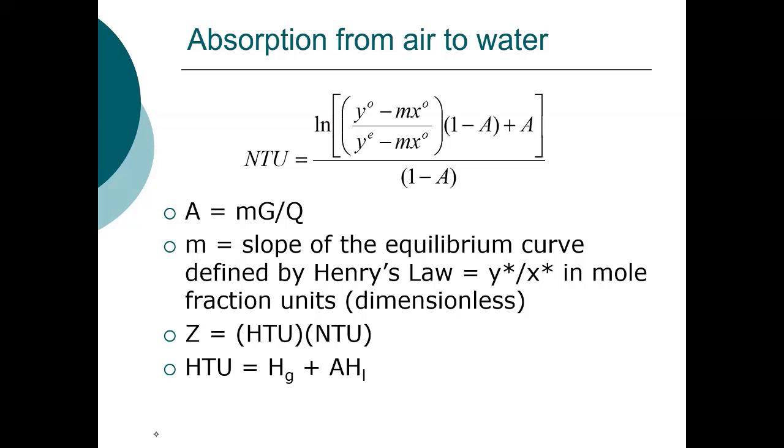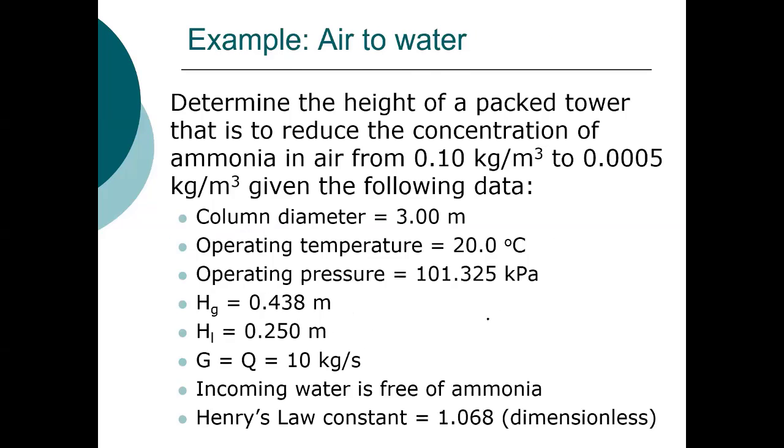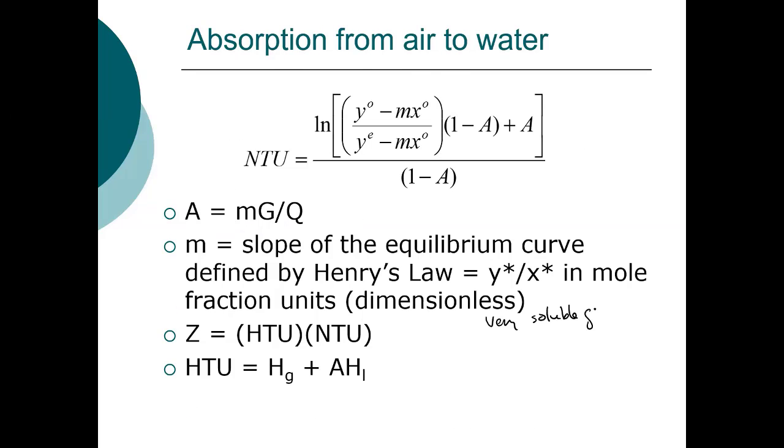And here, the height of the transfer unit is given in terms of parameters that would be supplied by the manufacturer. So it's related to the gas transfer rate, or the rate across the gas film, and the rate across the liquid film. If we have very soluble gases, then the liquid resistance is much less than the gas resistance.